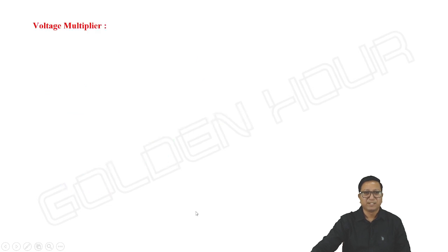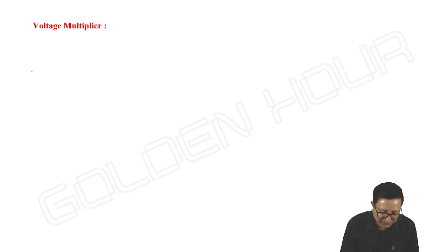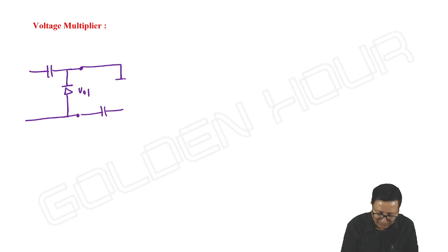Based on that, now instead of doubler, tripler, quadrupler, etc., I am writing a generalized voltage multiplier. So, I am starting with a positive clamper. You can start with a positive or negative clamper, anything. So, this is the output, which is acting as input to a negative clamper, and the negative clamper output is acting as input to another positive clamper.